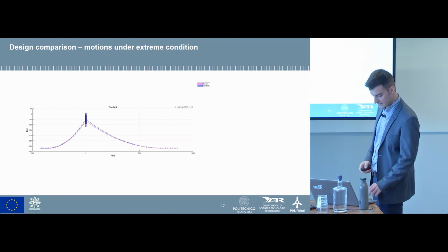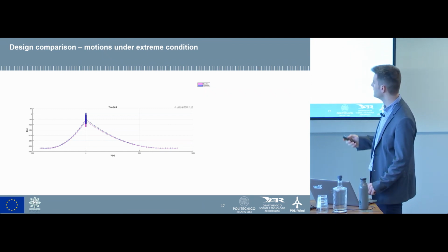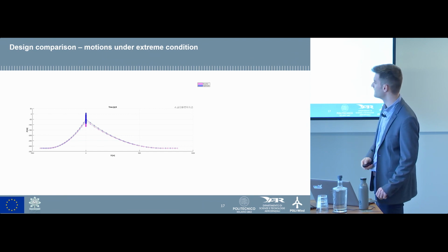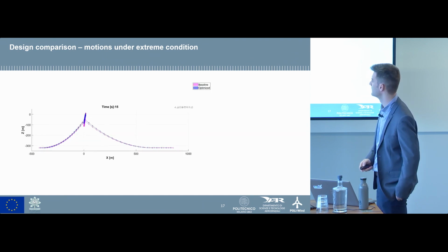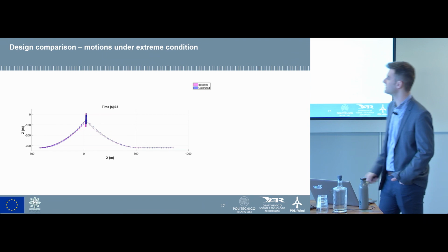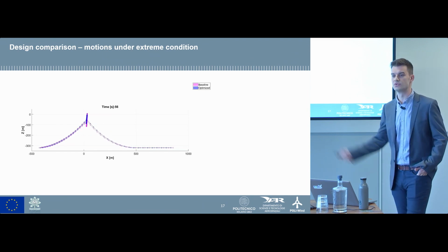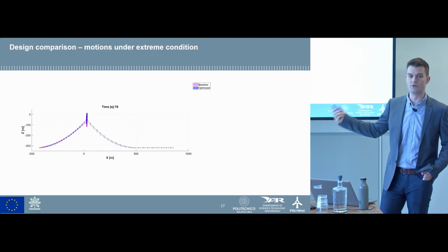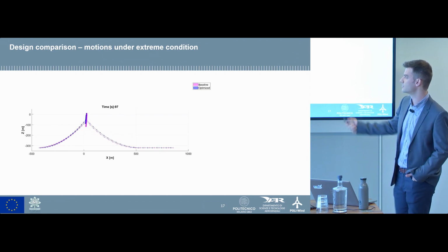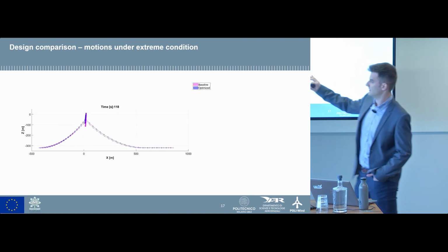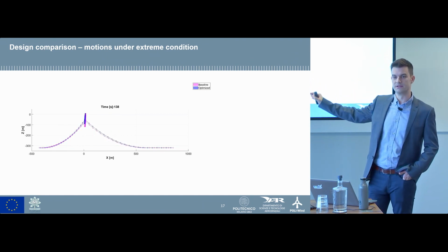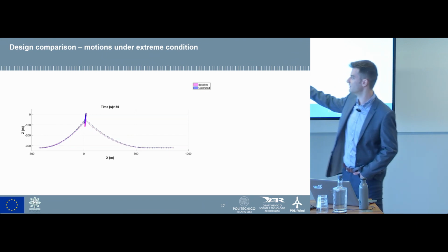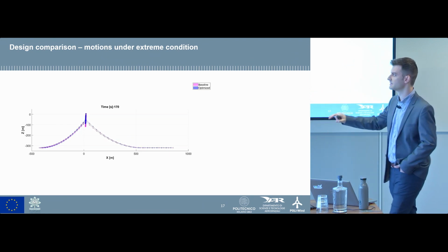So here we can have a look at the simulation of a time series that is coming from the EC3. So here, no power production, the turbine is parked in a storm condition. The simulation includes the turbine system itself. Here we are only visualizing the hydrodynamic parts.